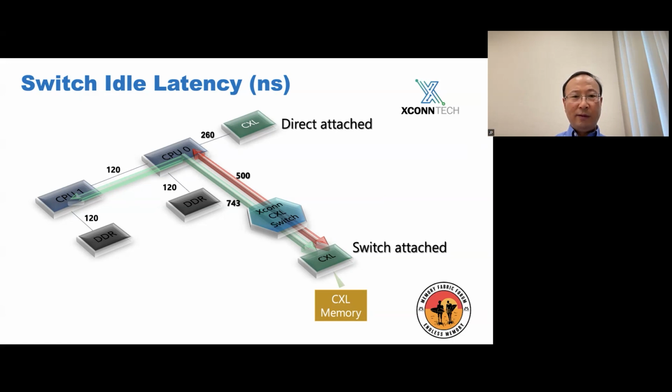The round trip read latency from CPU 0, which is directly attached to the switch, into the CXL memory is about 500 nanoseconds, where you see for the directly attached CXL device it is about 260.